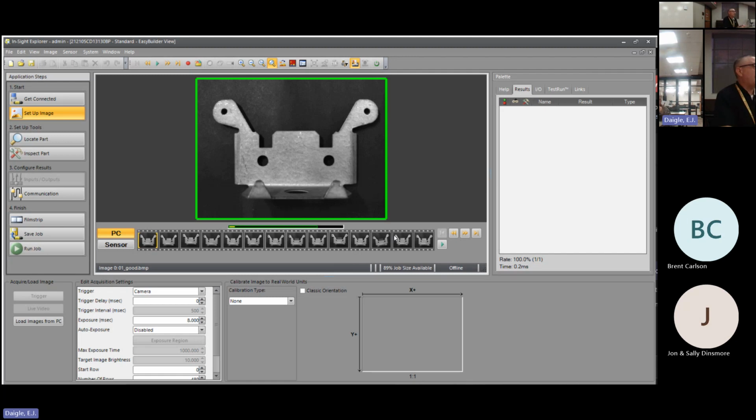So with inductive, you're going to have to have brass, steel. You might be able to do aluminum with an inductive sensor, but an inductive sensor is kind of like trying to create a magnetic field, right? You're disrupting a magnetic field with metal. You're not disrupting it with plastic or something like that. Capacitive you do though. Yep.